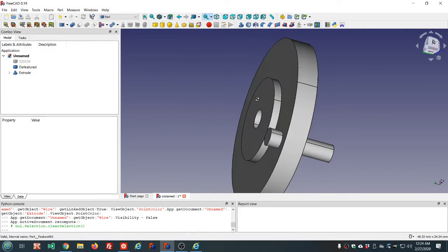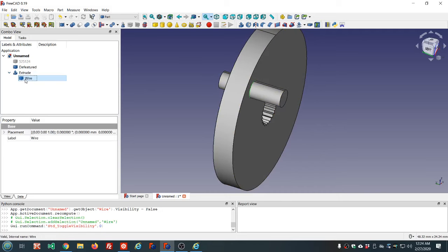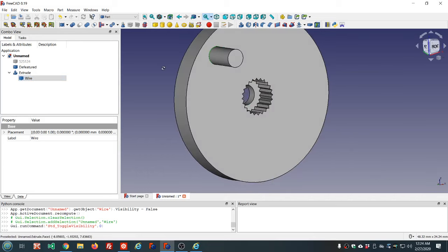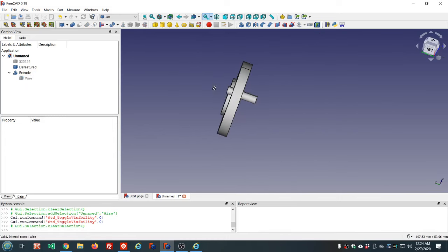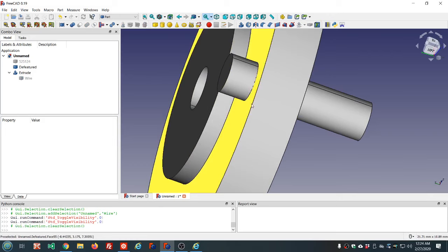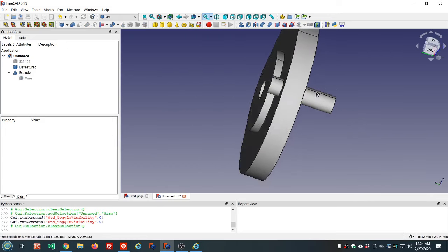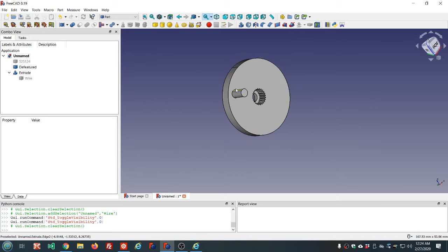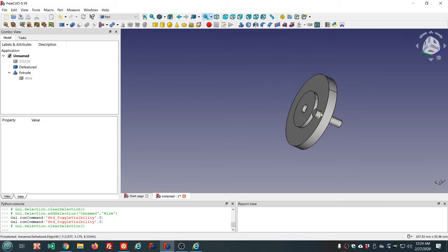Symmetrically, it pokes out of both sides, so we extruded 10 millimeters from the wire here, from there, in both directions. It's okay if it sticks out. It's even better if it does, because sometimes when you cut, if your faces are even right here, if they were coplanar, it's kind of rare, but it can occasionally cause a problem with the cut. You'll end up with a little bit of skin left.